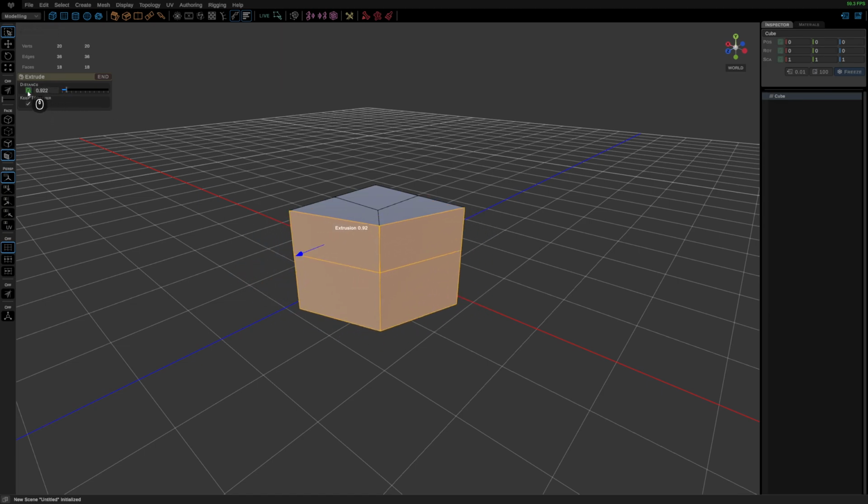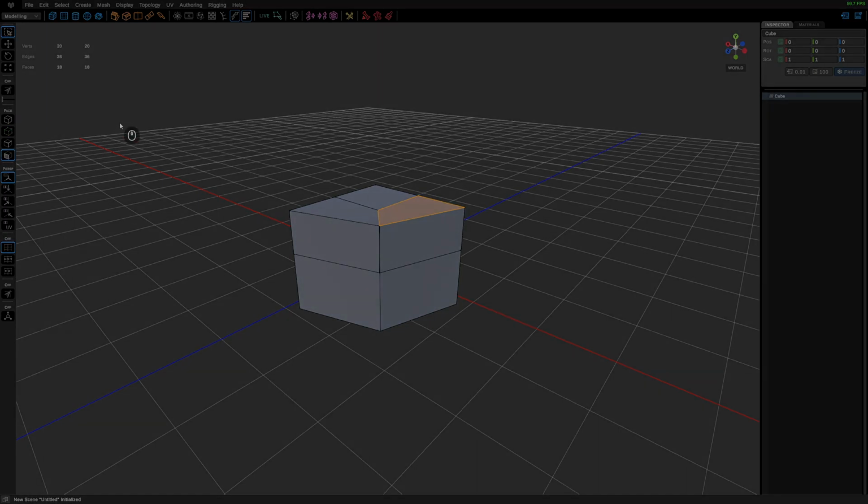We also have a keep together option. When this is disabled, the selected extruded faces are not kept together. You can freely toggle this option depending on the result you want. When we end the mode or exit the mode by deselecting or selecting a normal layer, face or object, the action panel exits as well. This is standard behavior for every poly modeling action. It is a destructive process.